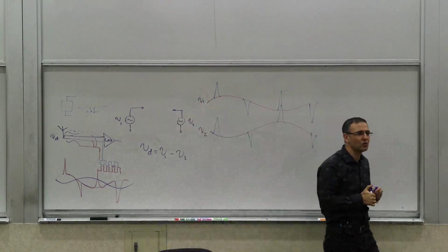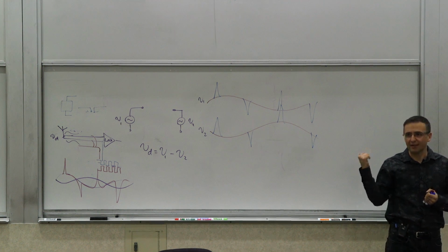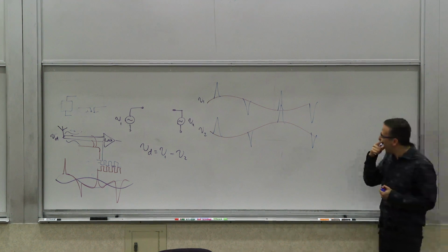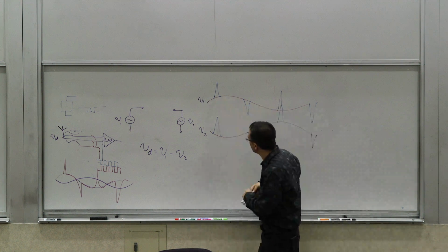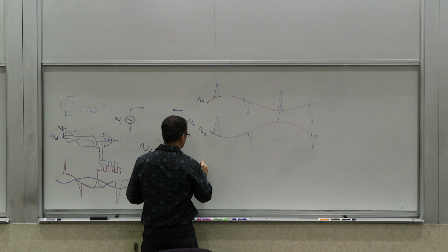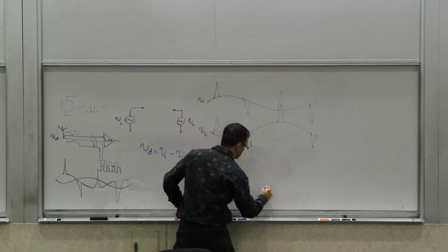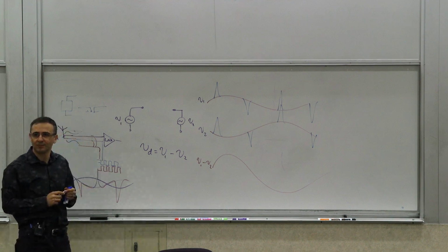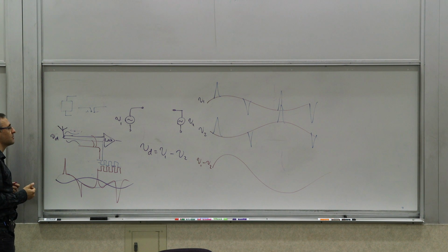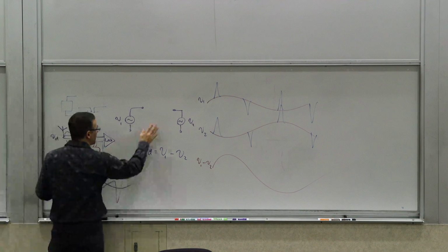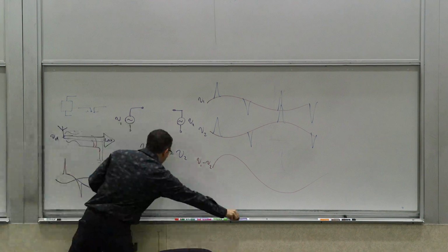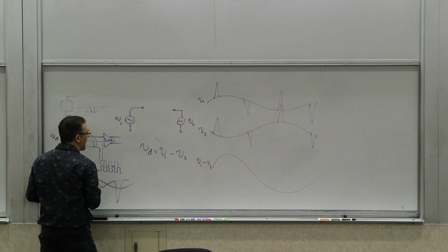The interference appears as something that's not in the difference, right? It's common to both of them. We call them common mode. It's common to both, and as a result, if I plot V1 minus V2, I'll see something like that with very little interference. So what if I could carry all of my signals in differential form, or basically as the difference of two different things? For that to happen, I need to have an amplifier that can amplify these things in a pair.